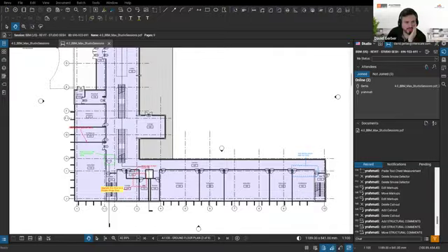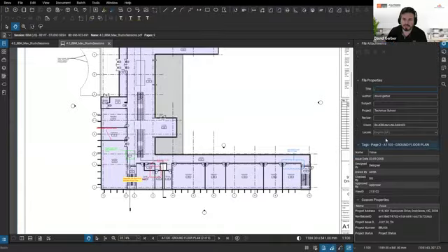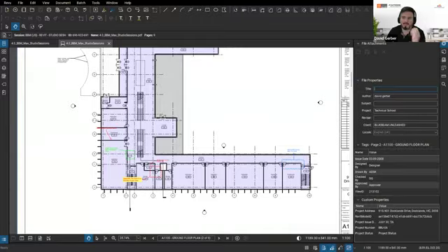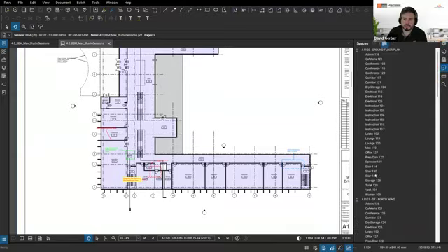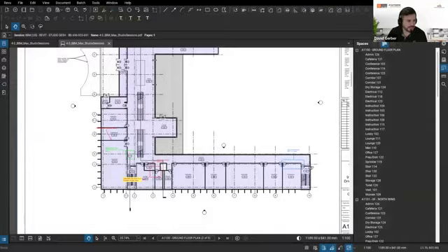I see one from Geo about breaking down quantities for each plan separately. For the legend, for example, that I did, you can say this is just for this page, or you can say all of them. So if you want, you could have it on your cover page and it'll calculate all of them, or you can do it per page. Just double check when you go to the properties of that legend, there'll be a mention that says just this page, for example, provided that's what you want. Or it could be spaces like we had here. If I put a markup, it's going to say ground floor admin room, so I can break it up that way as well. It depends how you want to break stuff up, but you could definitely do that.